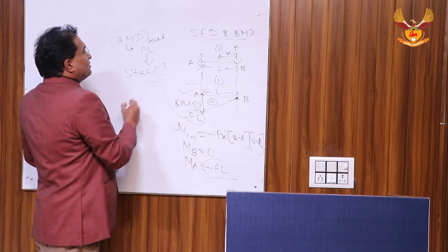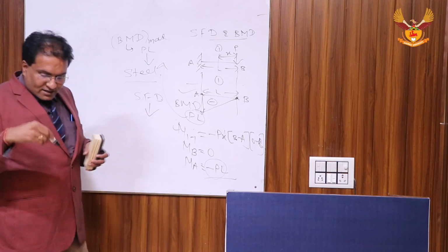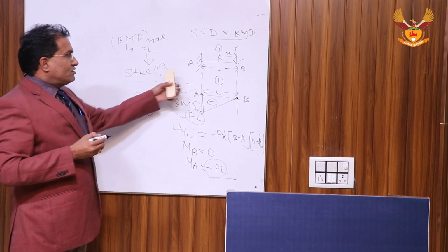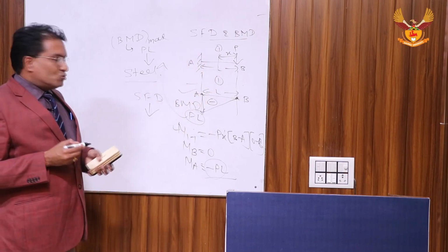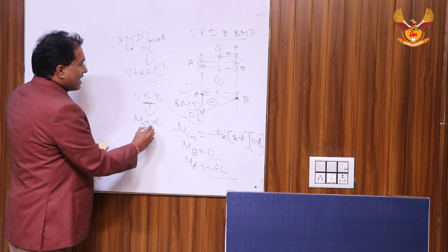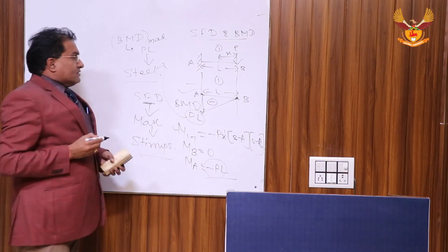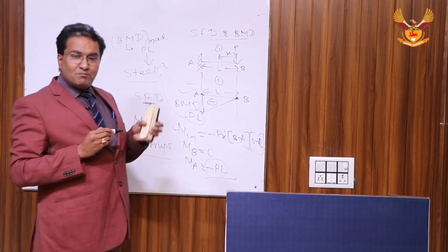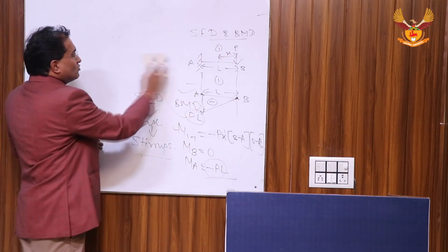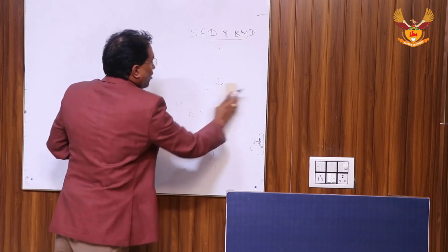Next, the significance of shear force diagram. In beam, if we want to design stirrups, then we should know the maximum shear force which is being developed in this beam due to loads. So from this shear force diagram, we will get the maximum value and we can design stirrups. So for designing of any beam, we need SFD and BMD both. From those values only we can provide steel and stirrups within the beam body.